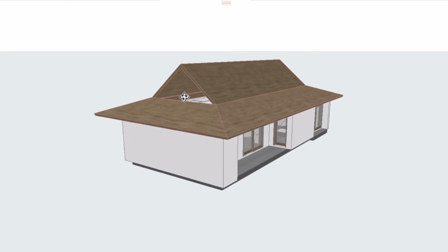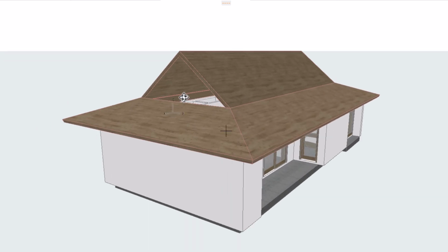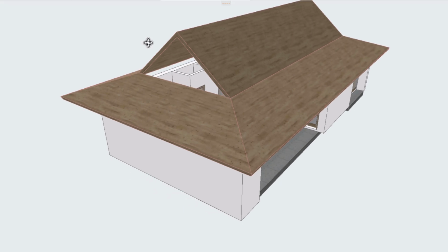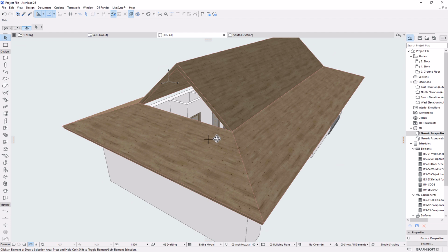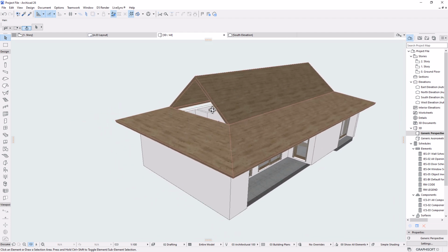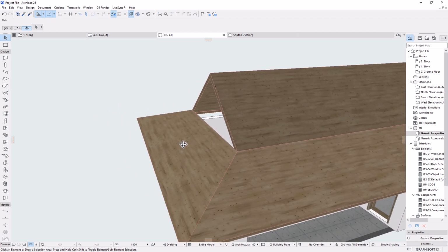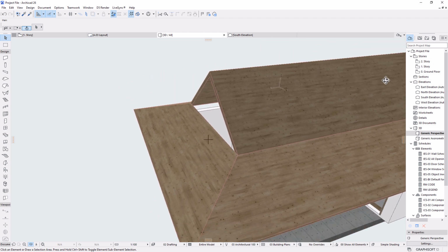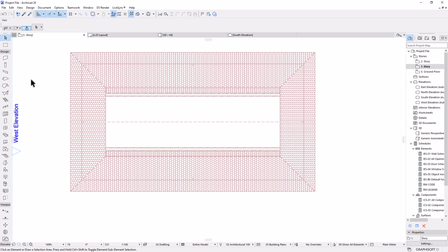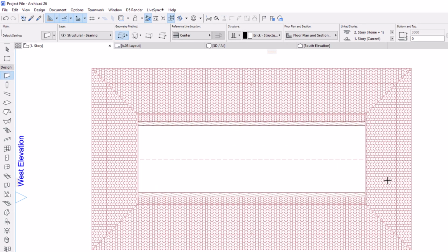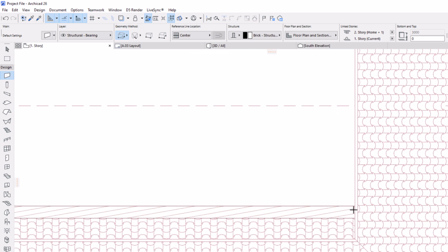So the question is, how can we detail this further and make it functional? I've seen we need to cover these openings created by this kind of style. In order for us to do that, we have to use a wall tool. I can do it on the plan view under the roof plan. All right, let's go back and activate the roof plan, and then activate the wall tool like I said, and then from here we need to do the geometry settings of our wall.